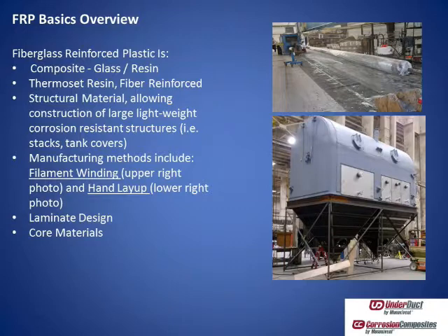And the theory is to put a laminate on the top and the bottom that are equal. And those are structural laminates, and the core will stiffen it. If you think of an I-beam where you have a flange and a web, the fiberglass skins would be the flanges, top and bottom. The core material creates what would be a web in an I-beam, in other words, the vertical element.